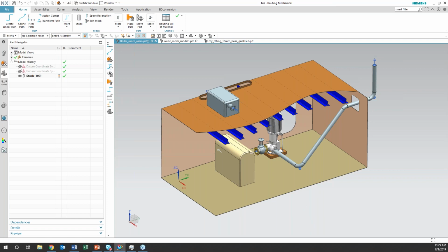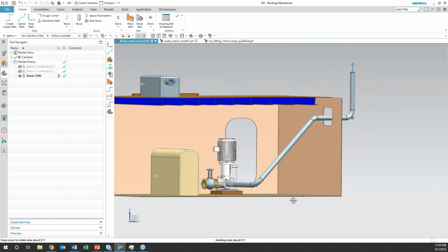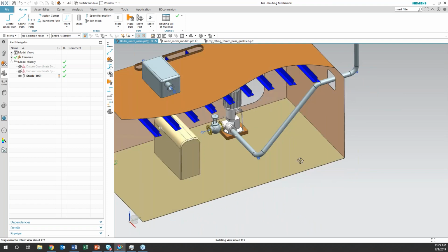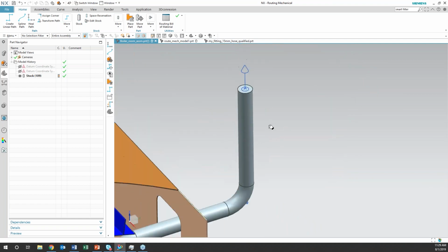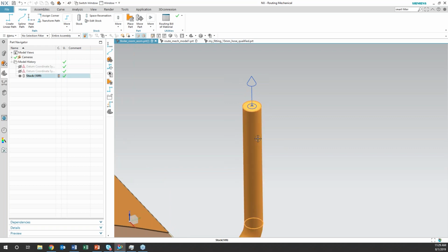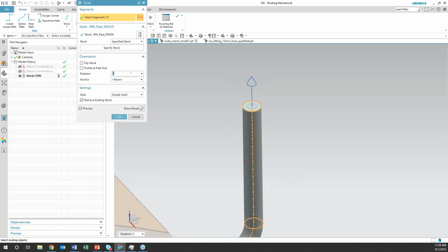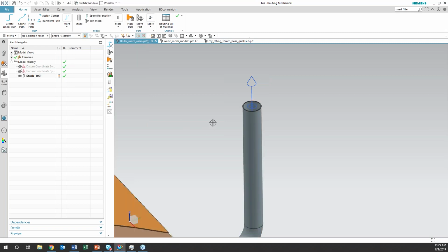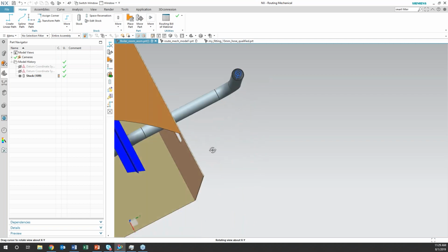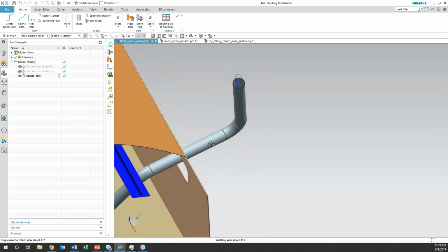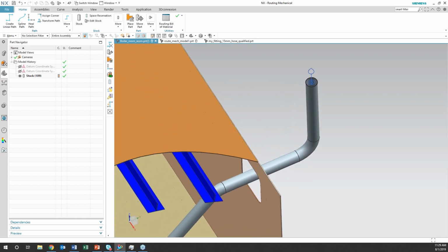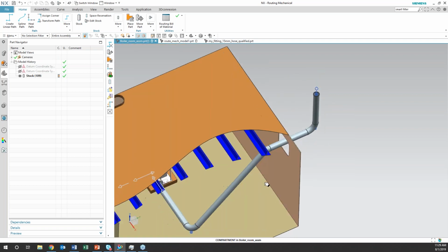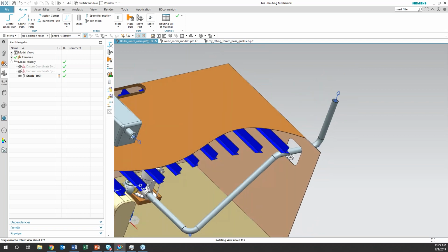Yes, good question. Actually, sometimes you want to see these hollow, so I have a view here. Right now it's just a cylinder, but all of these do have a definition. That's over here. It's in the settings, the style. If you go down to style here, you could just get a center line, but detailed solid allows this to be viewed as a hollow tube. It does take more space in large routes, virtual memory, GPU, if you have a really large assembly and you turn them all detailed.